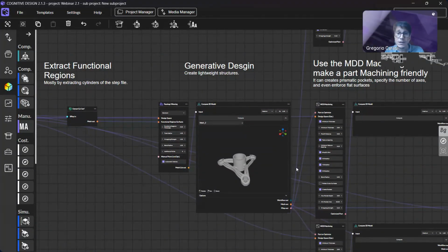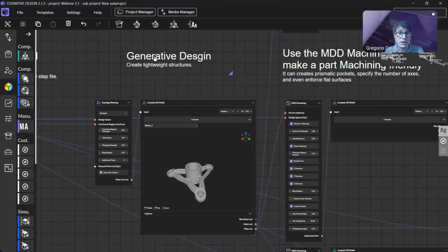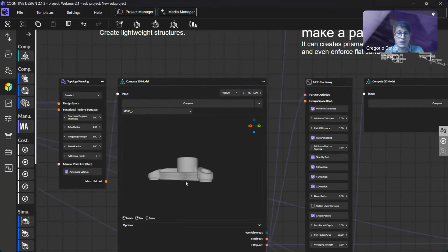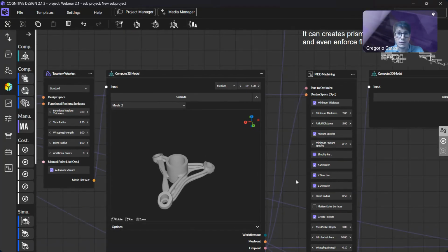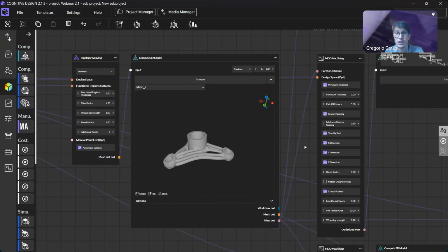So instead of, for example, doing a fully constrained topology optimization with manufacturing constraints, you can do a normal topology optimization, or in this case, run a topology weaving, and obtain a result that is often complex and usually more compatible with AM processes, but you want to make it compatible, for example, in this case, for machining.